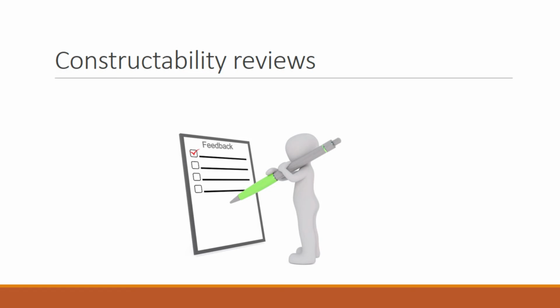Now overall, designs should be evaluated for constructability, taking into account factors including safety, cost, methods, and materials, as well as other construction-related limitations and potential for value engineering, which is meeting the needs of a user creatively while reducing cost at the same time. People with construction experience should attend these design review meetings and review drawings at various stages of review. And this might necessitate bringing in a contractor or consultant early, which is a construction management approach, also known as the design-build approach.